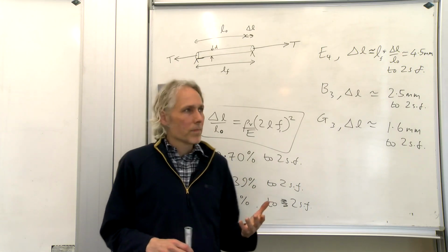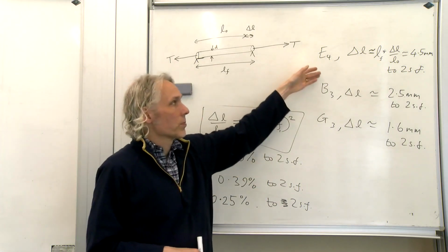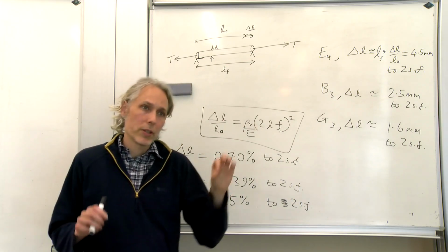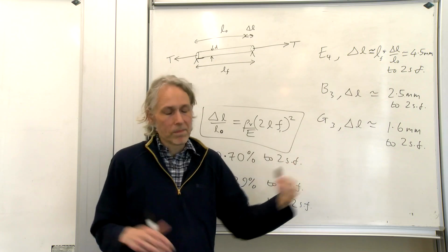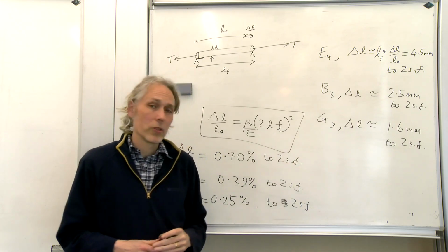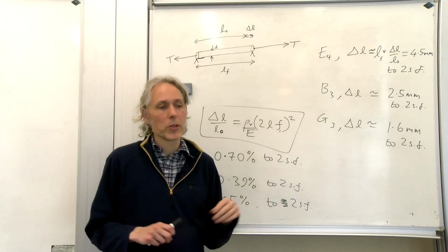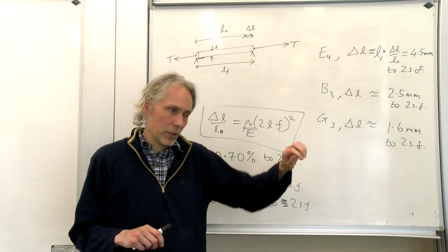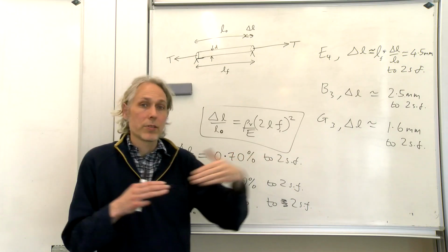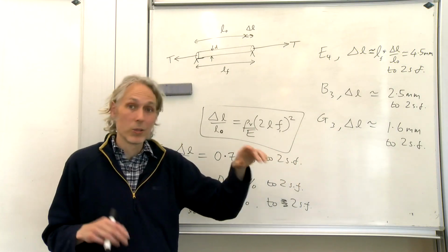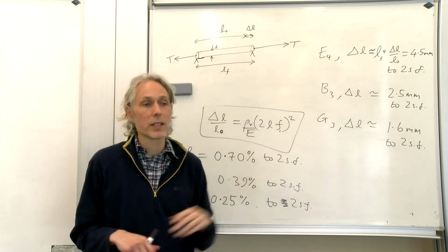Also, the string, particularly high E strings, they're operating quite close to the point where the string will start to elastically deform. So you get what's called strain hardening. The string initially, if it's not been up to pitch before, will, when you put it up to pitch, get a tiny bit thinner and longer, and it loses tension, and then you need to tighten it again.